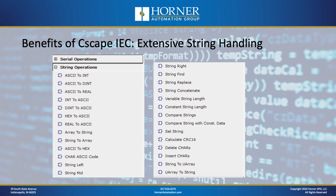Very. And so you get more instructions, including create CRC. If anybody's ever written logic to create their own checksum, that's a tedious task. So the fact that you have a function for that is fantastic. We're going to get into the structured text shortly, but also when I can get into a string byte by byte and adjust the string that way or compare against it, that's also very powerful. But just these functions alone that I can use in ladder, anytime I have an application where I have to do anything with strings, I want IEC. Makes a lot of sense.